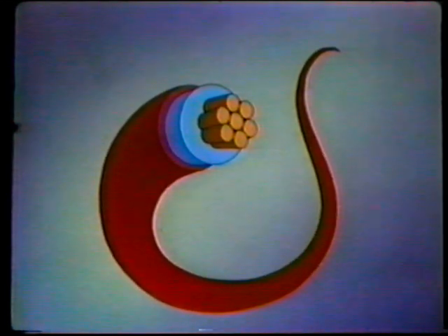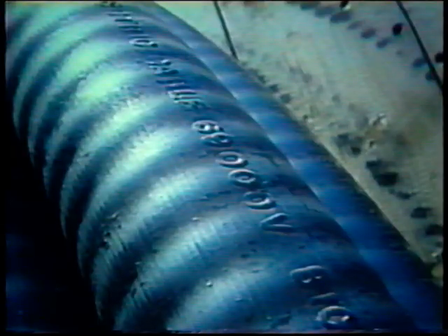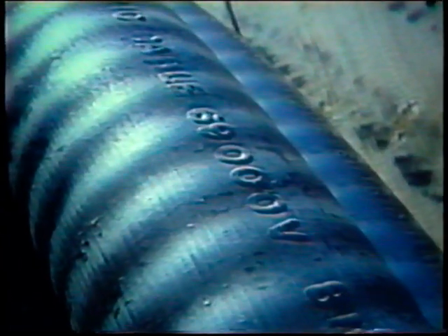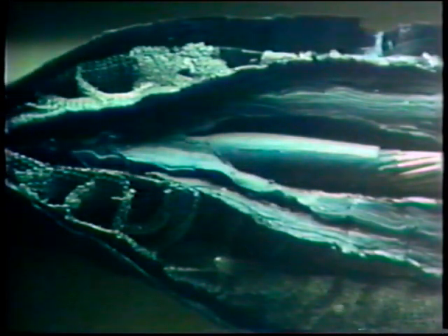Jackets are commonly made of hard plastic material which provides additional insulating properties and mechanical strength to a conductor. This is called a sheath. It's an additional covering applied over a jacket, mainly to provide extra mechanical protection. When you start working with high voltage installations, you'll find conductors and cables covered with multiple layers of insulating materials that range all the way from organic materials like rubber to complex synthetic materials developed to meet specialized needs.